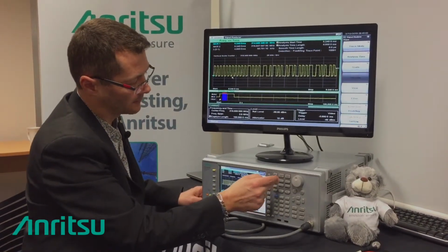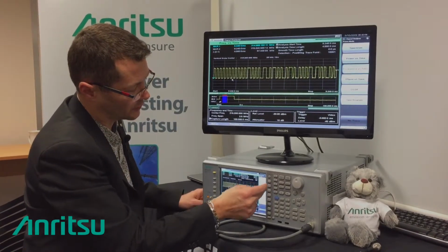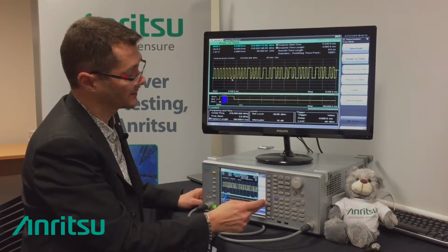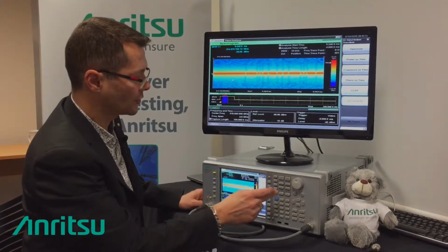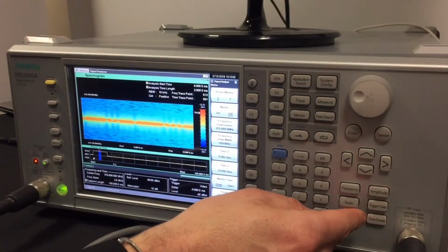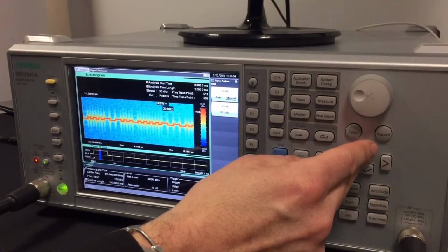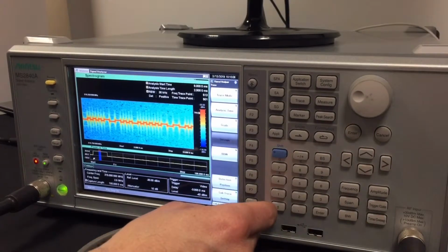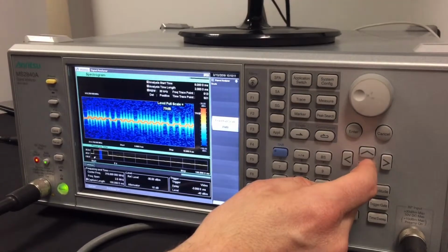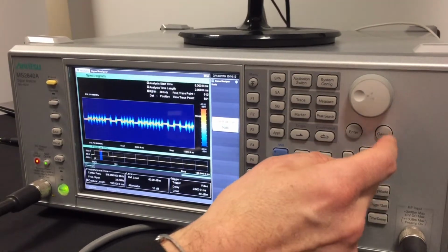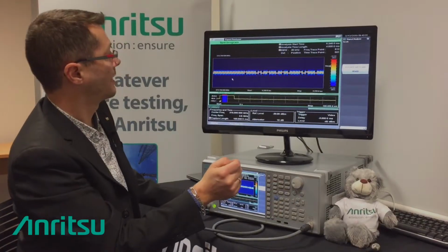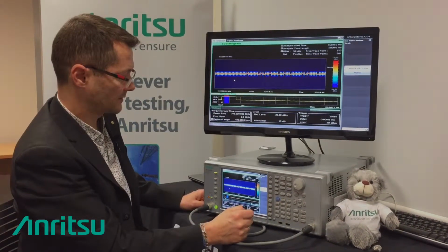and there is another kind of signal that we can see thanks to the VSA, which cannot be seen on a spectrum analyzer, that is the spectrogram. So I will change a bit, I will remove the marker, I will change a bit the RBW that I've been using. I can change the scale just to be sure that I can see the same kind of information that we were seeing on the frequency versus time display.